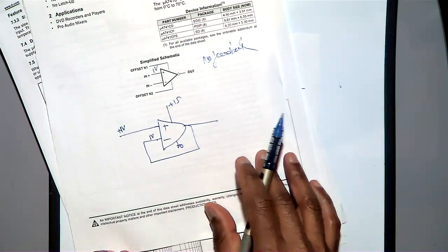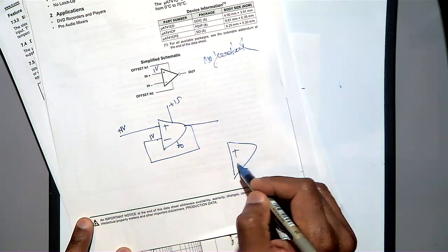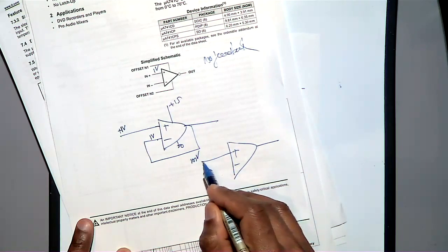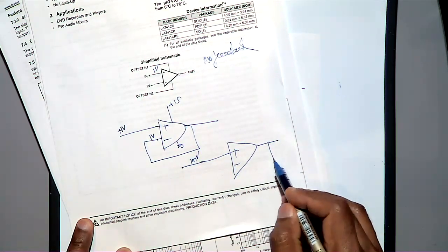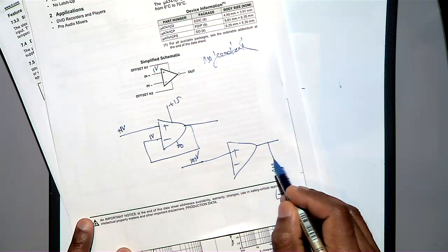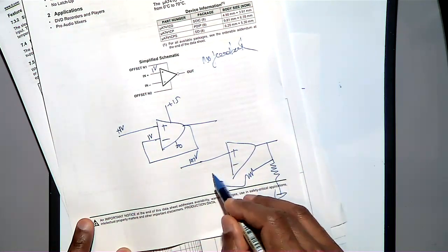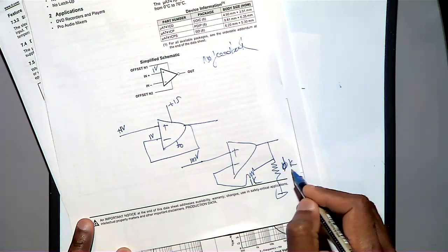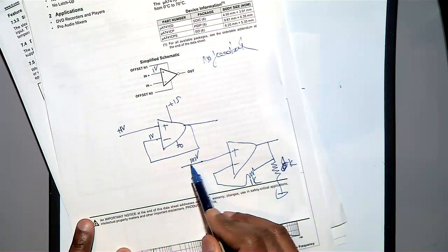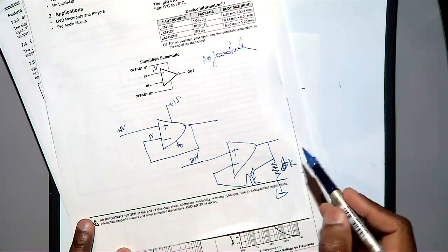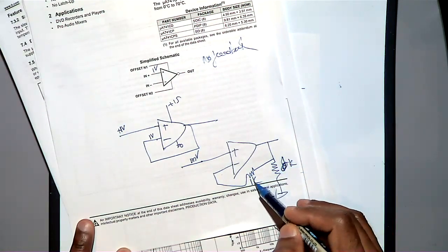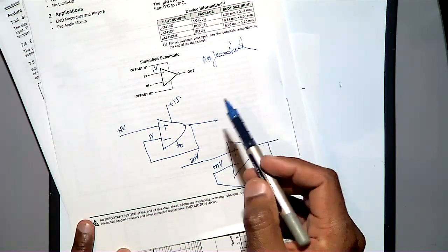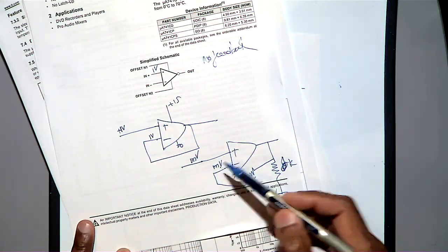Using this, I can design an amplifier. How? What I will do is I will take only 1 millivolt here, because I am going to amplify. Here I am going to make use of that operational amplifier as an amplifier. So then I am going to connect something like this. So this is 10K, or maybe you don't need 10K, this is 1K. If this is 1 millivolt, and this is 1K, this is 1K, then what is the voltage here? If this is 1 millivolt, the operational amplifier will make sure, because of the virtual short, that this is 1 millivolt. Then what is the voltage here?